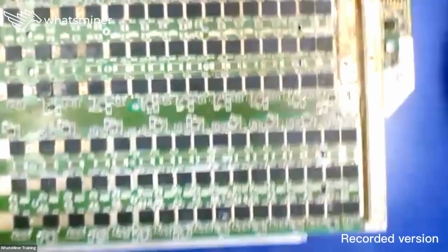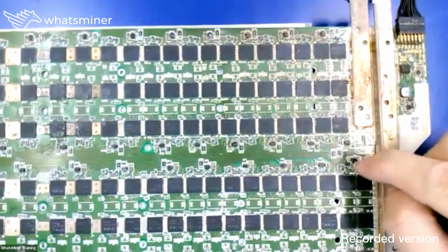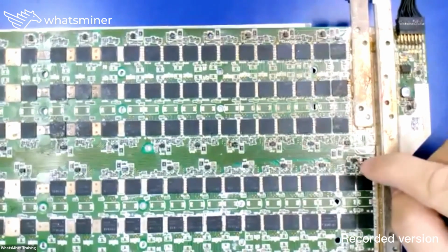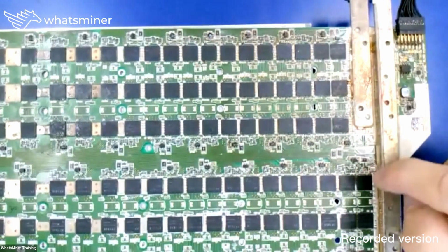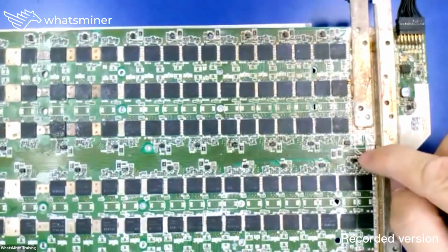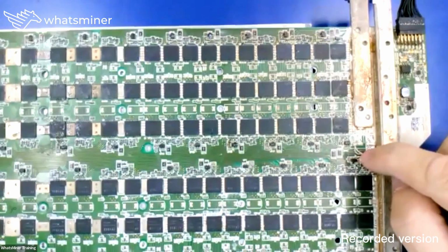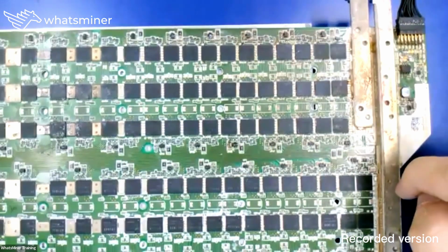Sometimes, when you repair the LDO circuit, the first step is to replace the LDO. If there is still a problem, you need to check the first pin to see if the input is enough or not. The input voltage should be at least over 2.2 volt, then it can make sure the LDO works normally.